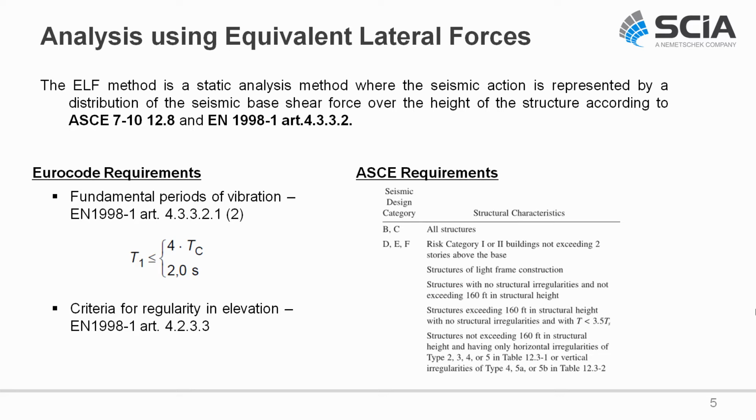However, using it in SCIA Engineer requires the input of some data related to dynamic analysis, like masses, and at least one combination of mass groups must be defined, as the calculation of the seismic equivalent lateral forces is based on the distribution of masses in the structure. The calculation of storey forces is based on the definition of storeys as well as the reduced system, which must therefore be defined in order to allow using the ELF analysis.